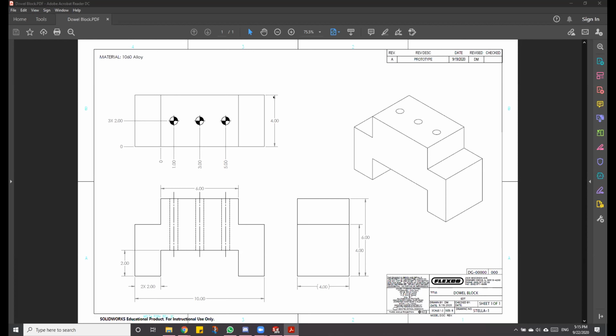So if you notice here, I have the width of the block, which is 4 inches. And I also have it here. Now this could sometimes confuse toolroom employees, like, oh, do you mean something different? Why is this here? So if you have a dimension doubled, make sure that you reference it. And there will be an option I will show you guys for parentheses.